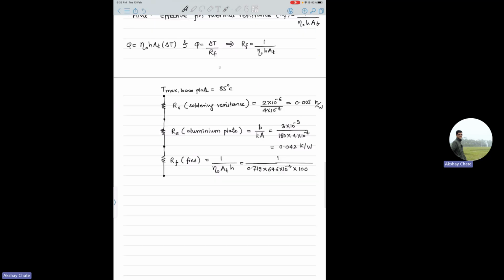Yes. So if you simplify, or you can do the calculations further, you should get this value approximately 2. Yeah, it should be, because minus 2, minus 4 and 100 gives you minus 2. So this will become 0.7. So 0.7 squared is 0.49. So 1 divided by 0.49 should be around 2. And then you have the ambient temperature, T infinity, which is given as 20 degrees. So this is your whole thermal resistance network.